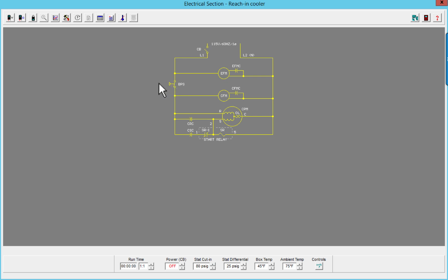When it drops below 35 degrees, or the pressure thereof, it opens. In this system, because it's commercial, like most commercial systems, the evaporator fan runs constantly. It's the only way we can circulate the air in this cooler over the evaporator to affect the refrigerant pressures. So the evaporator fan runs constantly. But my box temp is designed to be over 35 degrees.